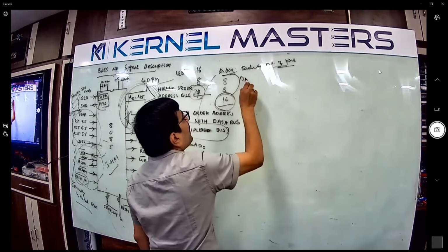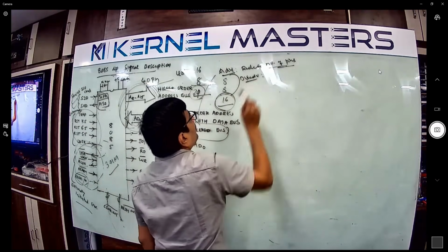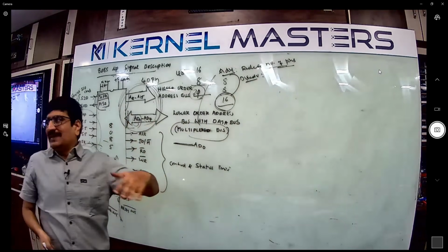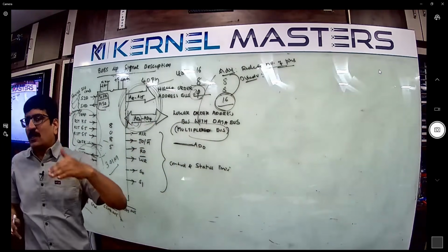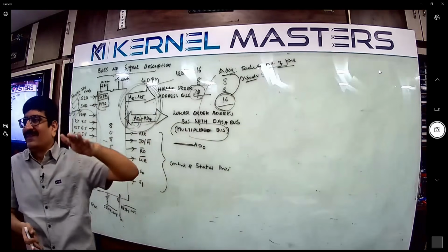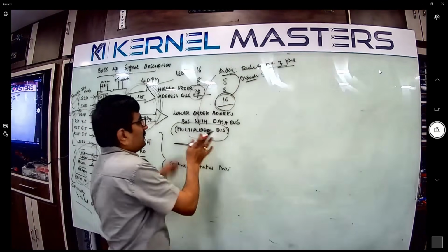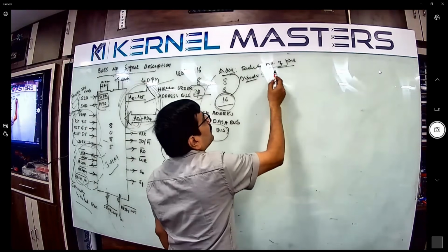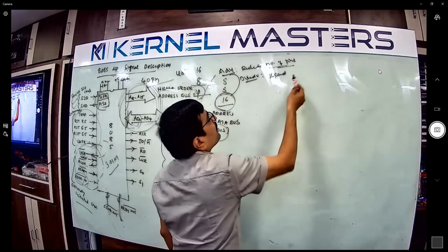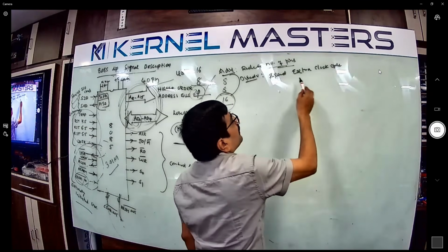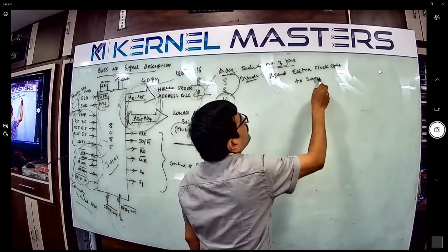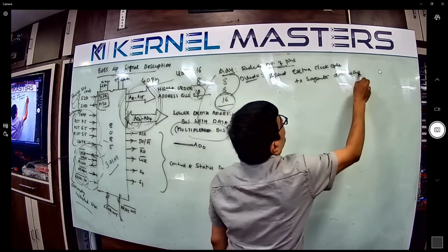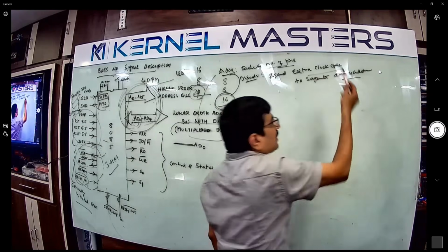But the drawback is also there. The disadvantage is that, because the same line carries address and data, it takes some time to separate them. We need to separate the address bus and the data bus. The microprocessor spends some extra clock cycle to separate both. An extra time period, a clock cycle, to separate the data and address bus.